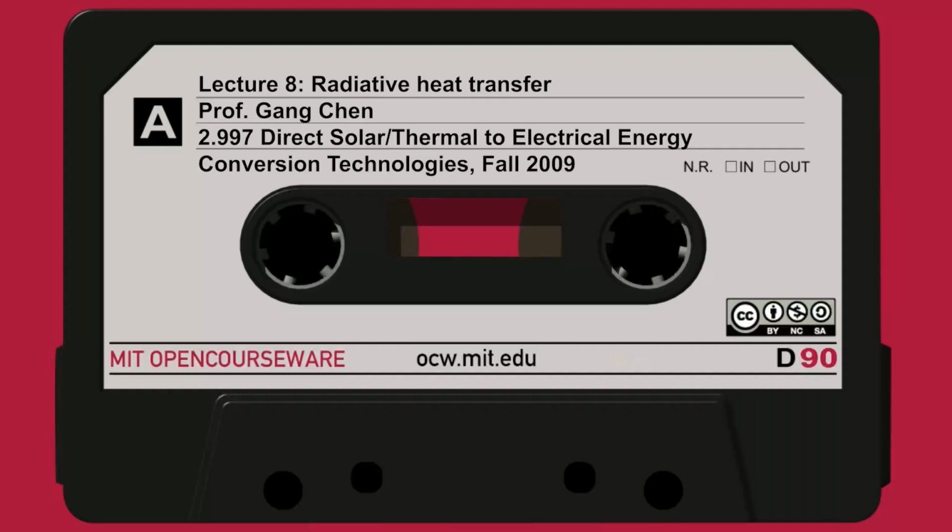And first I want to say how much heat can go from the sun to this absorber. Here I'm doing two black bodies, so black body radiation from the sun is sigma T^4. You can see now I don't have this very small view factor. I'm just doing two parallel plates, okay?